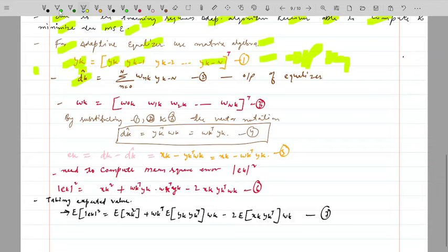That is how we can find it. Basically we take the summation, where the small n goes from 0 to capital N, of w n of k times y of k minus n. Here w represents the weights of n values. n also has values from 0 to capital N, and may be a scalar, and k represents the input time delays, y of k up to y of k minus n.